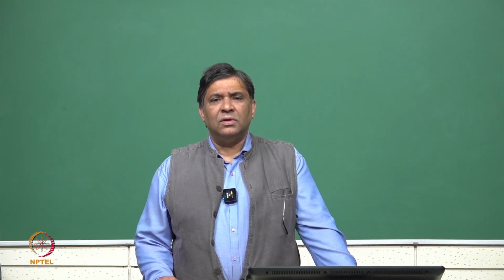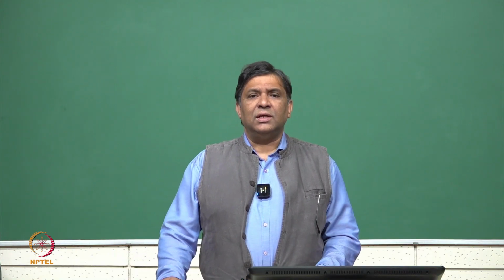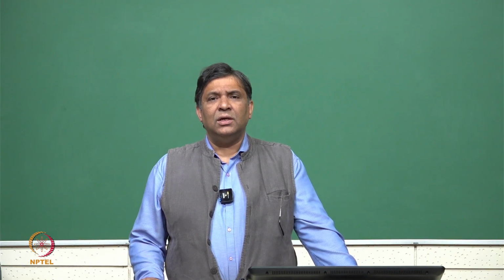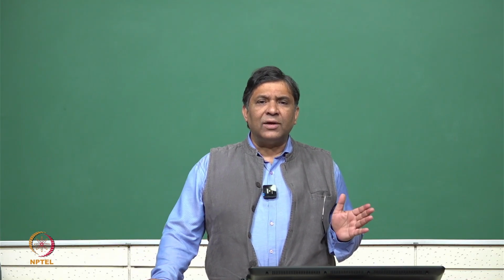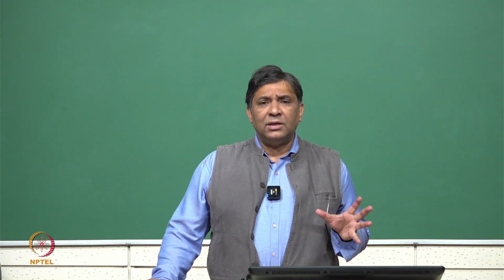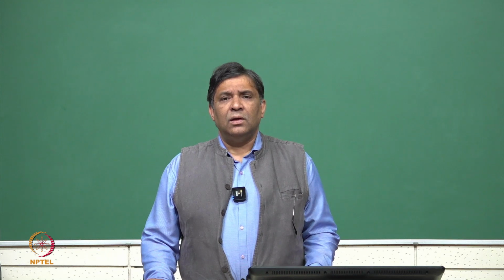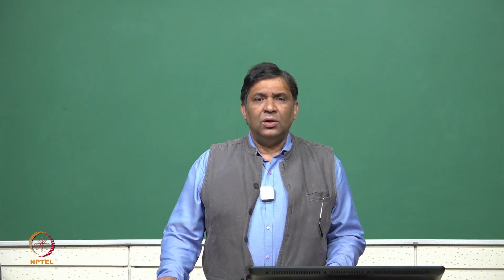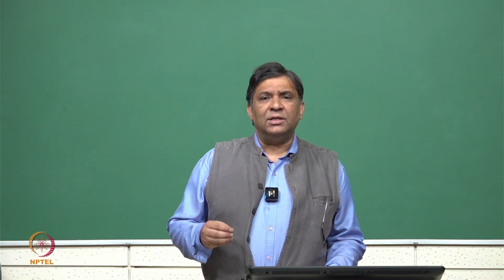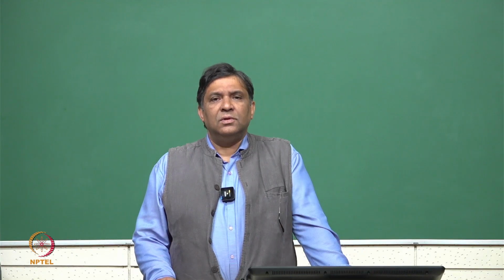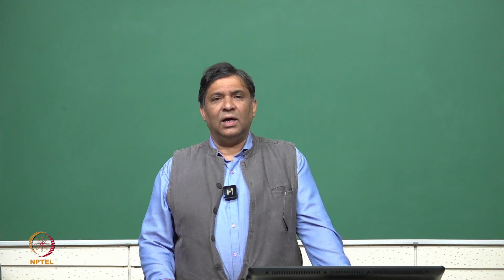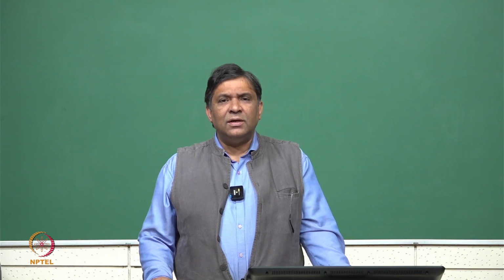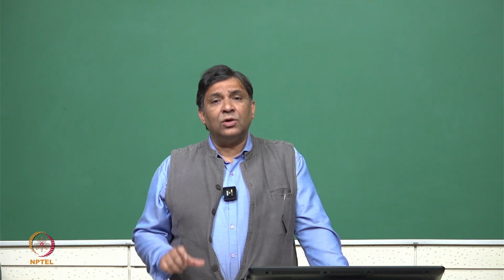In this case again the heat energy is used, but an EMF is not developed by keeping two junctions at two different temperatures. Instead, one particular electrode is maintained at high temperature, and this is known as the emitter, and another electrode is maintained at cold temperature, this is the collector. Whenever the emitter is heated, it generates electrons, and these electrons go towards the collector, and then go through an outer circuit where a load is connected, and a voltage is developed across this load.